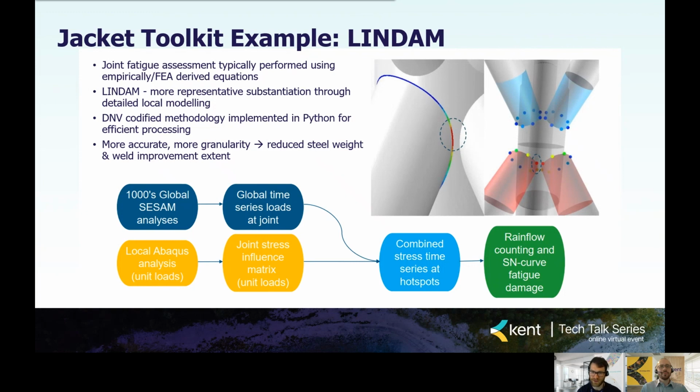But LINDAM allows for more representative substantiation through detailed local modeling, so either in shells or solid elements. Is the screenshot on the right here, where you analyze the stress concentration factors directly. And it follows the DNV codified approach, which has been implemented in Python for efficient processing.